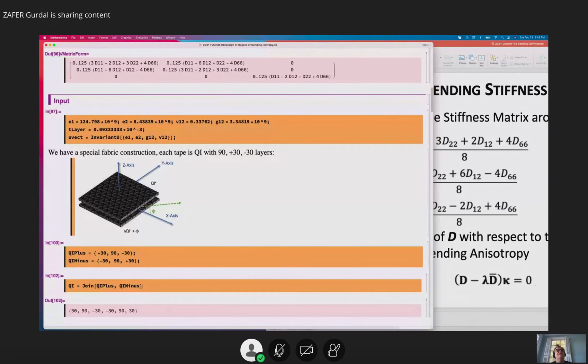So if you rotate these around this z-axis, the in-plane properties of this are isotropic, in-plane properties of this are isotropic. So whether you turn this ply in that direction or you keep this, it doesn't make any difference. In-plane properties remain isotropic. But if you look at the bending properties, you're going to see that when you take two of these together, you rotate the top one by an angle phi, you're actually also changing the bending stiffness matrix of this.